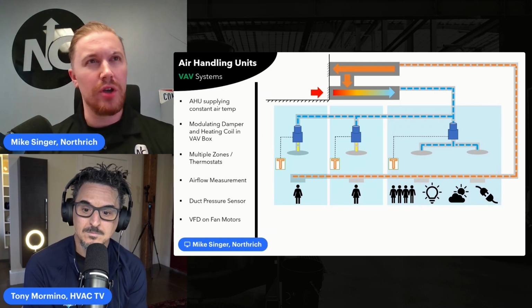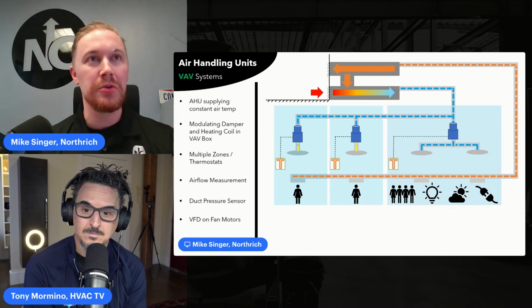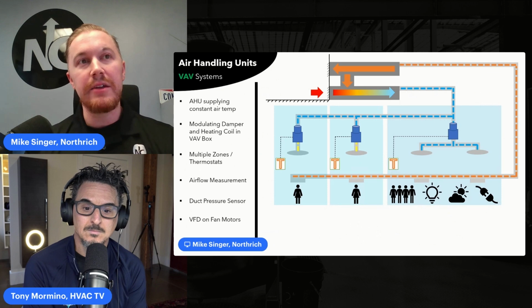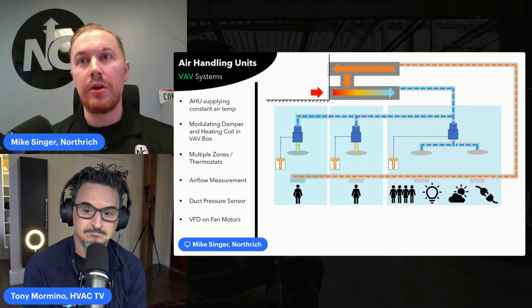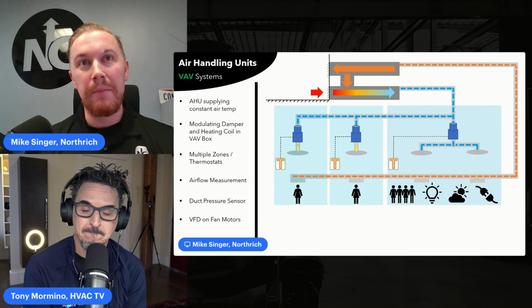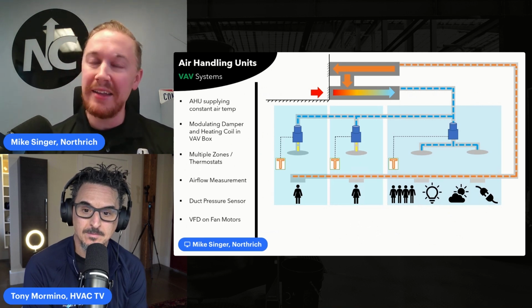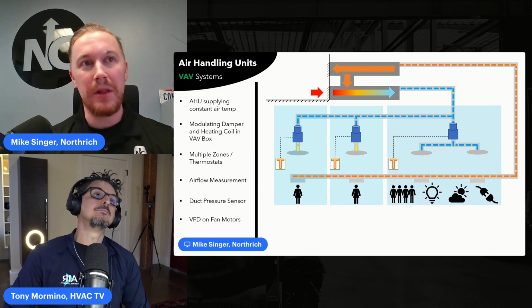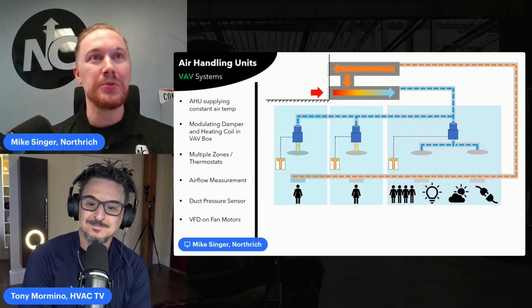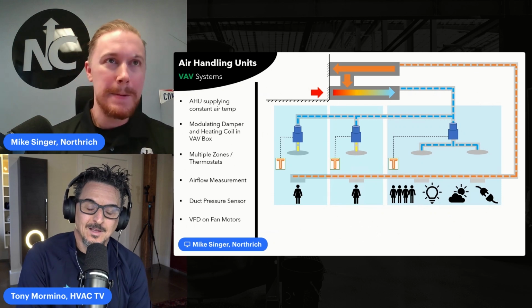And a good rule of thumb, if you're running that low temp, make sure you're specifying a 2 or 3 row VAV reheat coil. When you're running 180 and 160 return on that boiler water, sure, a one row coil will cut it. But as we get lower on that boiler supply temperature, we have to get more surface area on that coil to transfer the heat.